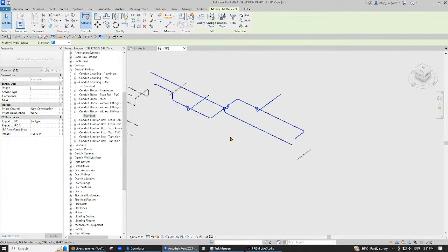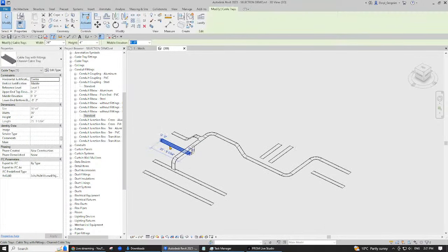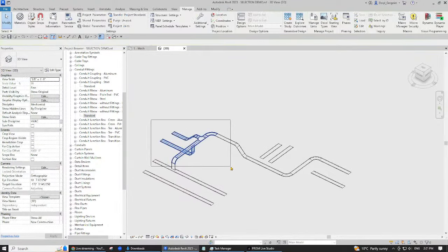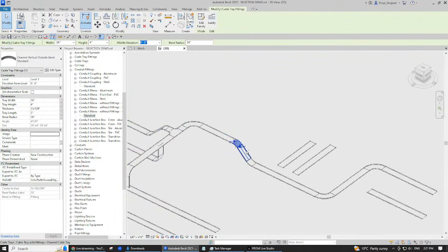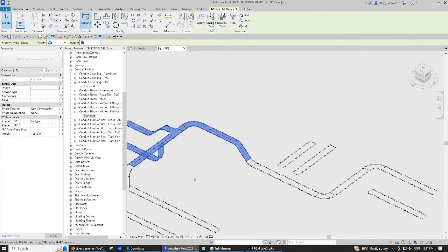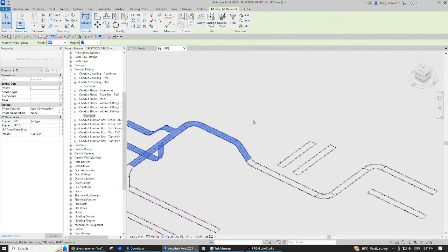Kind of like a block in a way. And then I can go move it or change it or do whatever I want. So whenever you hand pick something, and you grab a bunch of stuff, and then you go Control and you window and you take your time to grab some things, and then you want to say, boy, that took a while, I wish I could retain this, you can by saving it and calling it selection cable tray 2 or cable tray 1, and that's it.